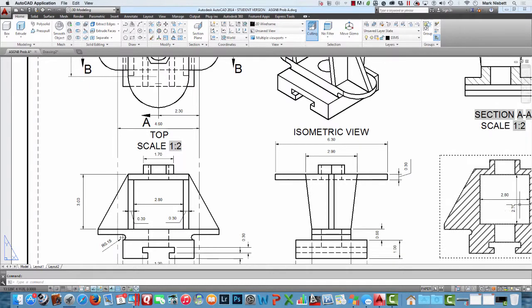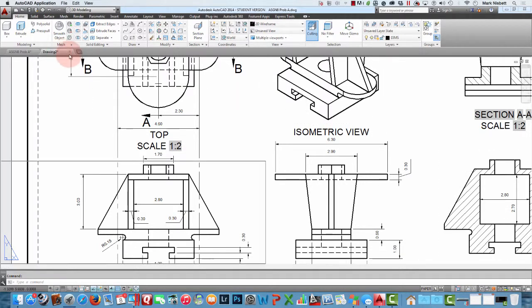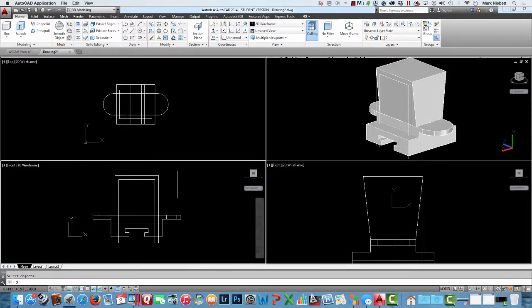We can see that here in the cross section. So we can come over here now and use our offset command of 2.7 and offset that down like that. And then we should be able to trim that again. We can trim these lines off, okay, like that. We can erase these construction lines, don't need those anymore.